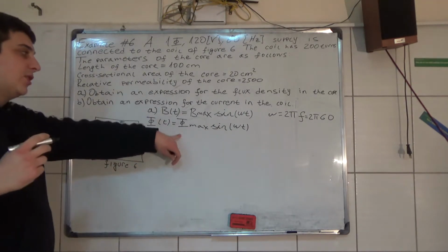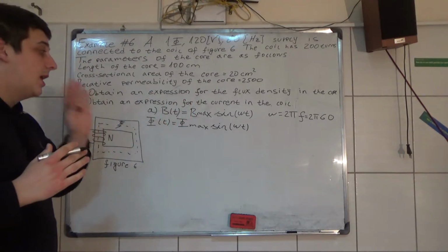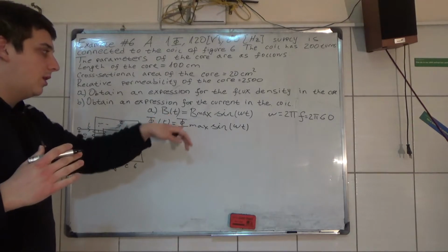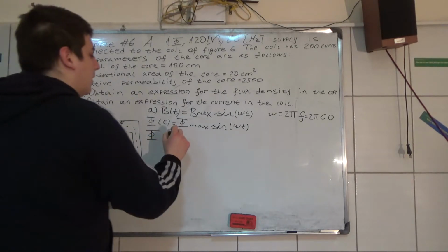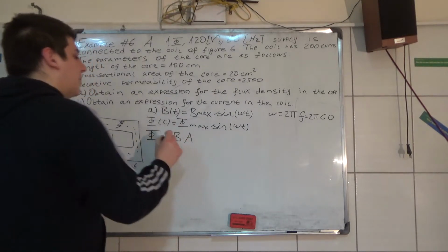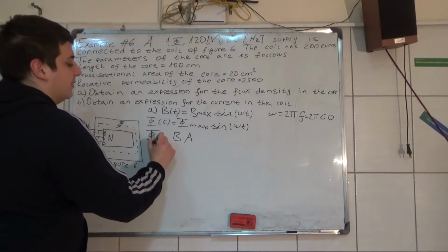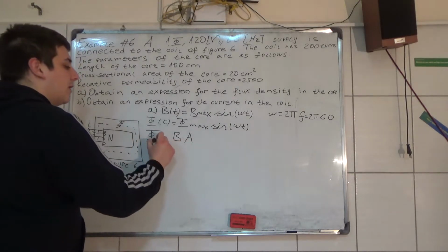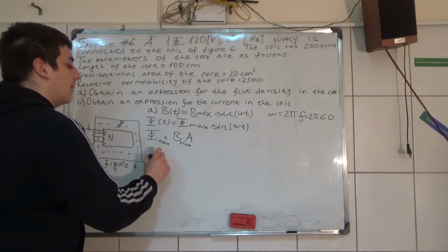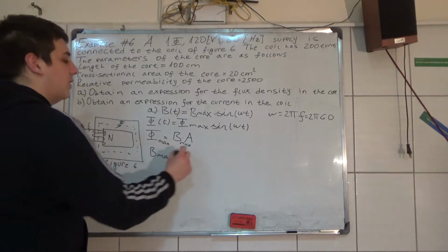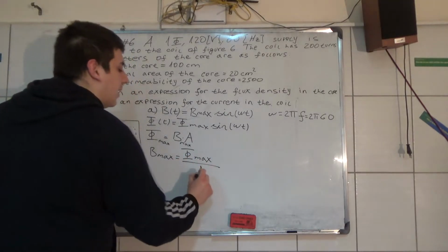Now how can we measure this? Well, these things are both in phase. You know that the formula for the flux is equal to B times the area, the magnetic flux density times the area, but also that this is equal for the flux maximum to B maximum times the area, and then you get that the B maximum is equal to the flux maximum divided by the area.